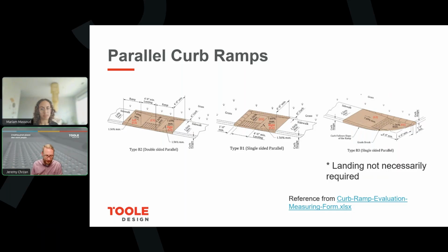It's just that because it's a landing, it means it's a relatively shallow slope. And so that's what I was saying, that if stormwater is flowing along the curb line and it's up against a vertical surface, and then all of a sudden that vertical surface isn't there and you have a relatively flat area, it does mean that stormwater wants to spread out and start to get into a portion of the landing itself. And that's why it would be preferable to install a drainage facility upstream of this location so that the volume of stormwater that's reaching the curb ramp is minimized. All right. Wonderful.